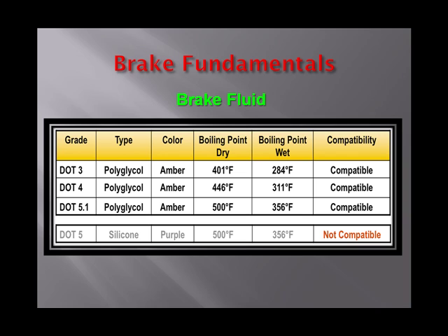There is a new brake fluid out, DOT5.1, which is also polyglycol and is used in some Ford systems. Make note, use only approved brake fluid in a brake system. Any other lubricant, such as power steering fluid, automatic transmission fluid, or engine oil, which is petroleum-based, will react with the rubber components of the brake system and cause them to swell and disintegrate. Some vehicles have fluid level sensors that provide the driver with a message when the brake fluid is low.